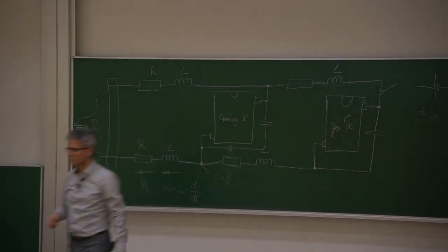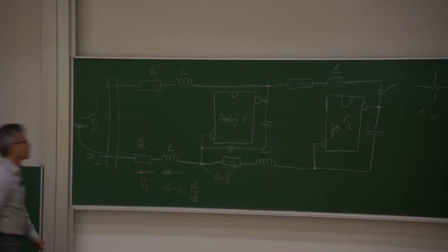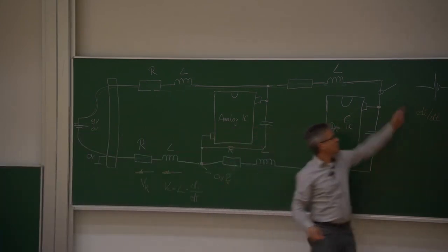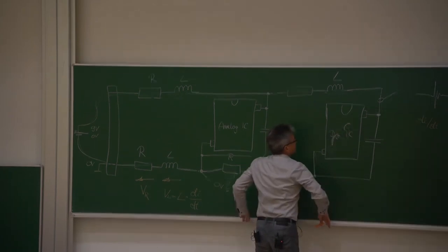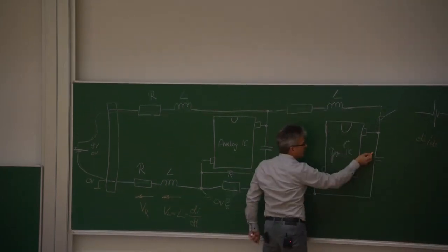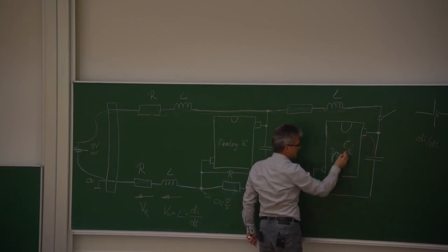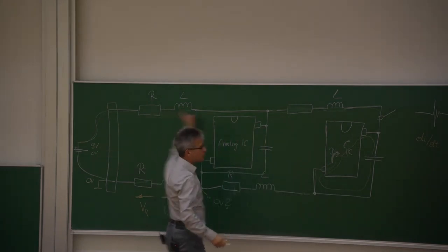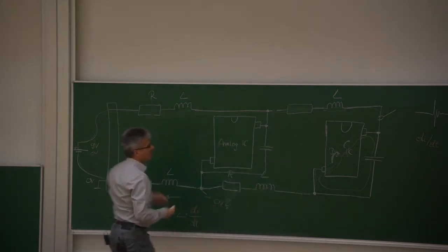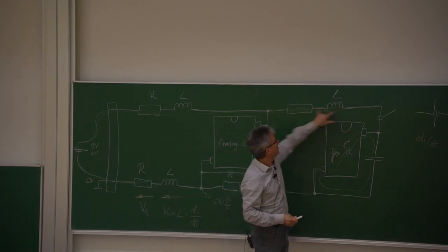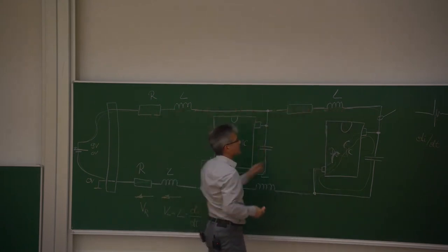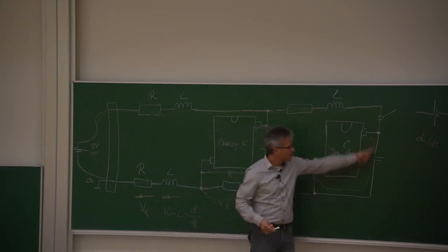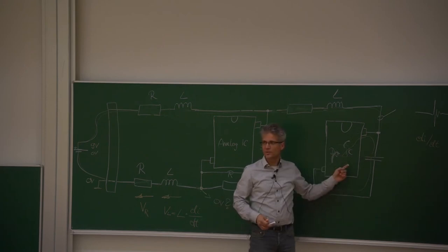Okay, what does the decoupling capacitor do and why does it help? Because now this switching activity that is generated here, these current spikes, if you have designed it in the right way, they can come out of the decoupling capacitor. So the high frequency current is not flowing over the whole loop area anymore, because there are inductances and resistances, so the impedance in the direction of the battery is much bigger than the impedance over the capacitor.